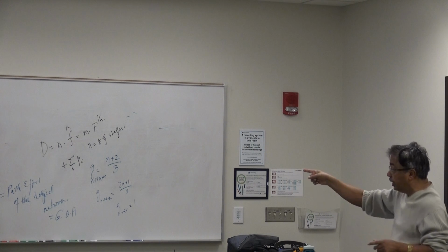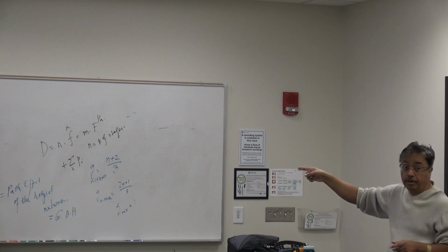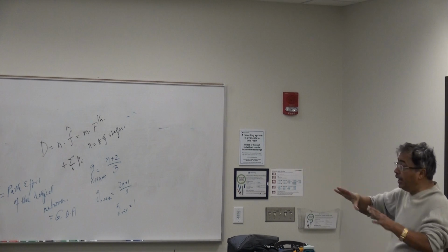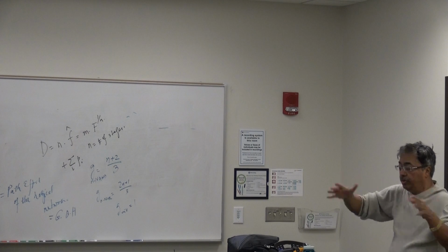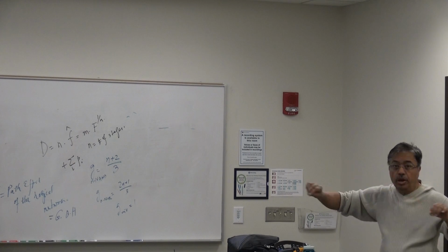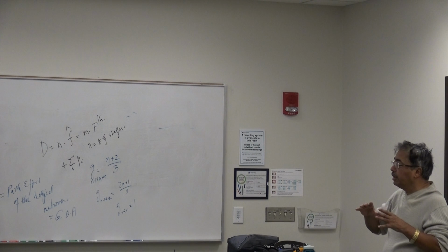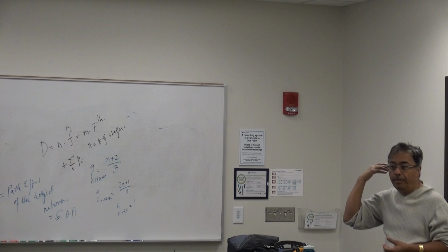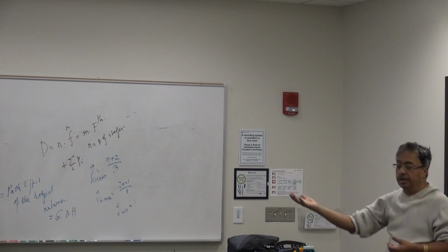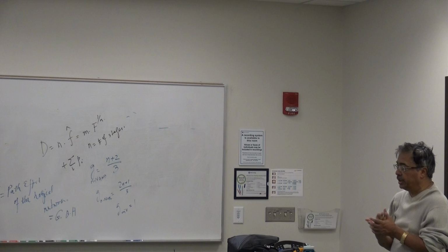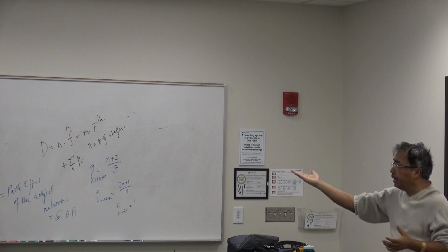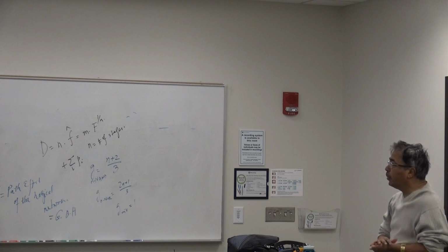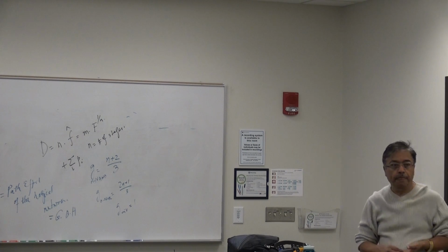Because this does not account for the interconnect delay. You understand? This does not account for the interconnect delay. So if I have an adder, which we'll talk about later, which requires long interconnect, obviously that's going to slow down when you actually fabricate it. So as an engineer, you'll have to apply those extraneous parameters in the optimization process. So interconnect delay is not included here. Another thing is that, what else is not included here? Anybody?